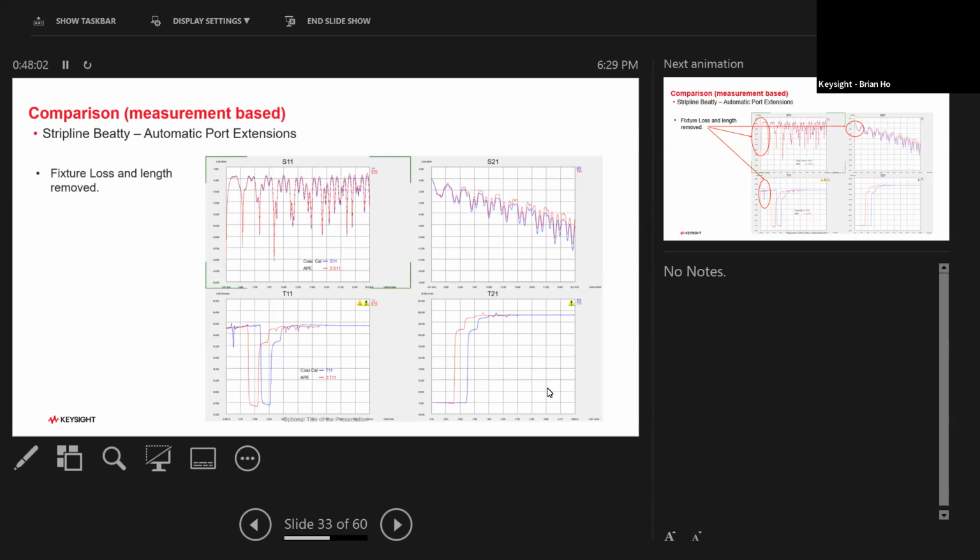That is probably the connector that we're looking at, and the red is the de-embedded portion, which includes the connector. If you look at the red, you can notice that this divot is in the negative time. So what it did is shift it away from positive, so we're not even considering this as part of the measurement. You can see that it de-embedded this out of the equation, so that now we know that we're directly looking at the unit, not the fixture.